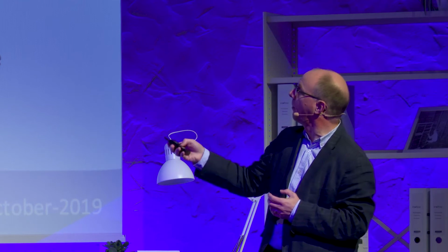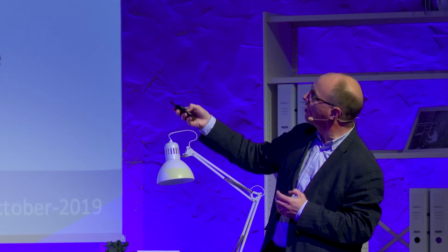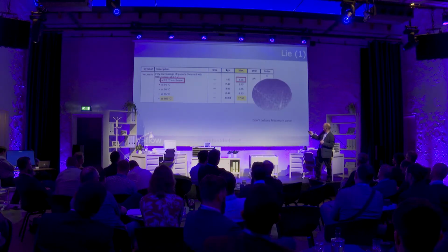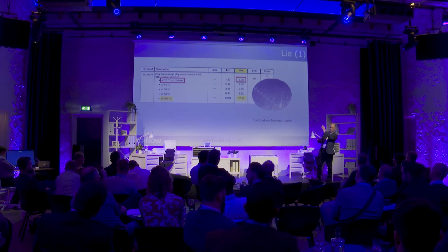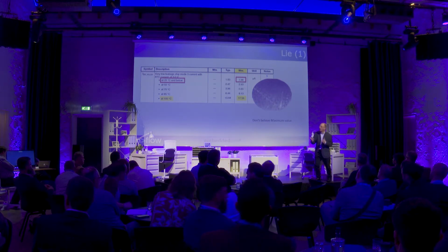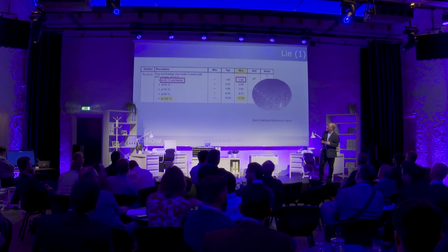Well, 90 nanometer is a very, very leaky semiconductor process. So as the temperature rises, the chip leaks and leaks and leaks. So if you do your design based on this number, 2 microamps in stop mode, that's fine at 25 degrees, but definitely not at 105 degrees.